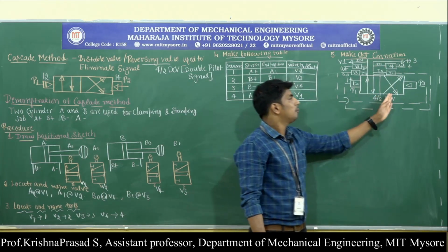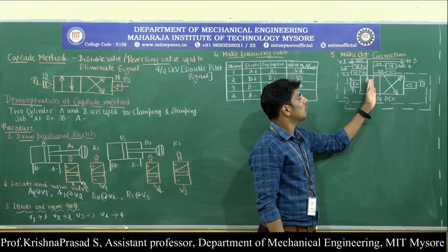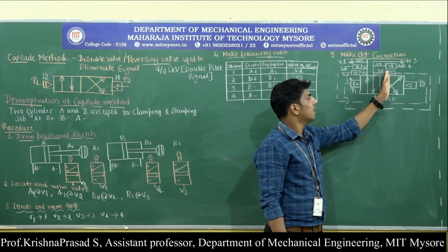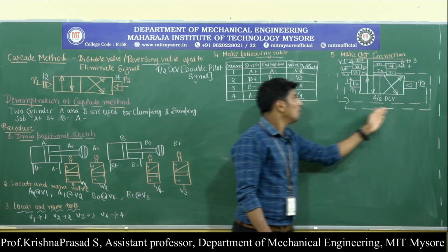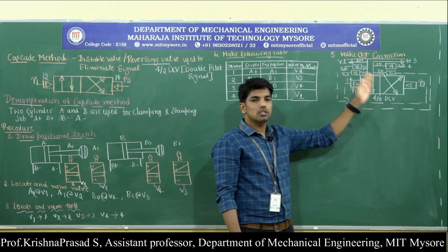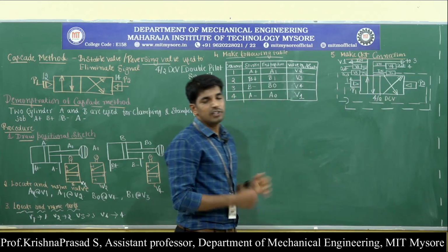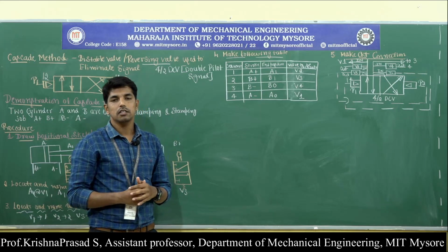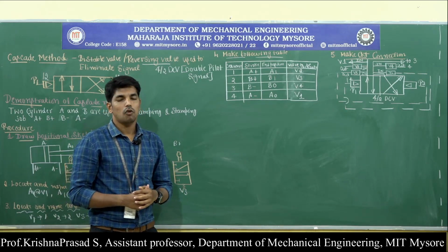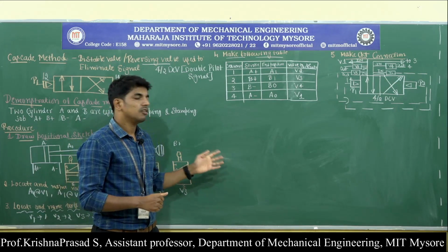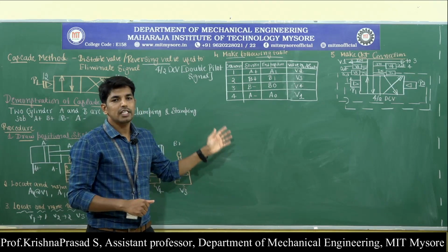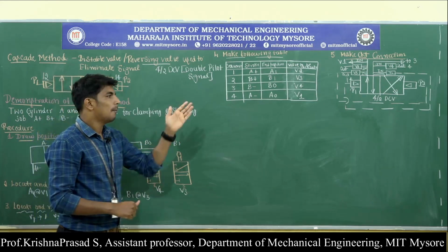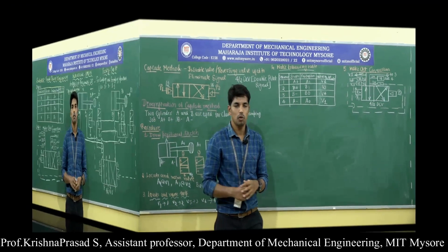Then finally the pressurized air goes from the input to the output through V4, and finally it again reaches V1 through pilot signal P1. So this is the circuit connection we need to observe for change over the signal, in order to avoid the signal overlap and signal conflict problem. Next we are going to analyze the pneumatic circuit for the clamping and stamping operation with the help of the bistable valve or reversing valve.